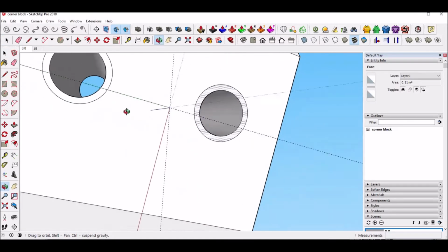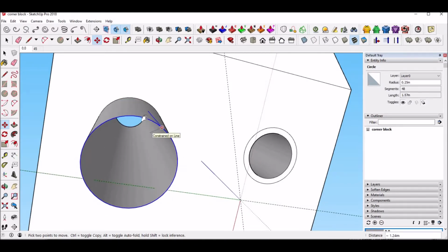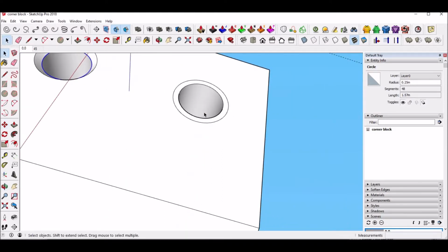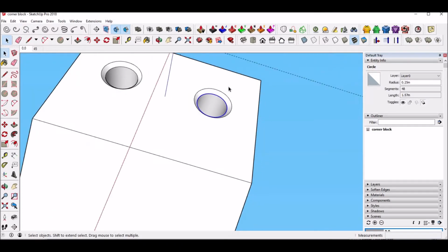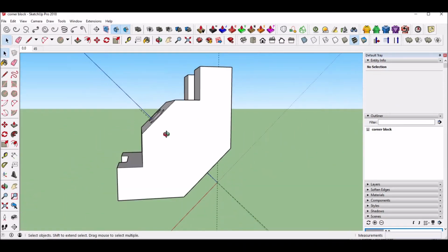Okay. Now, click the move tool. Whoops, click this circle, then the move tool, then Alt, and then the up arrow to force it in that direction. Ooh, we need to rotate our camera a little bit. Okay. 0.06. Perfect. M for move. Do the same thing. Nope. Click this first, then M for move. Alt. Hit the up arrow. 0.06. Boom. Okay. Now we have our chamfers, nice and clean.